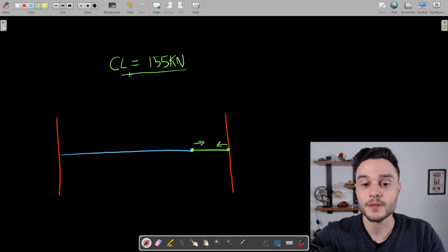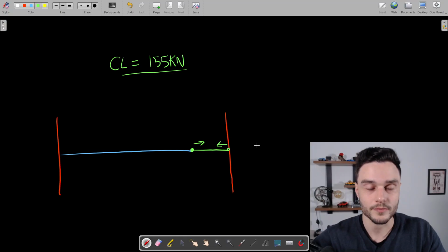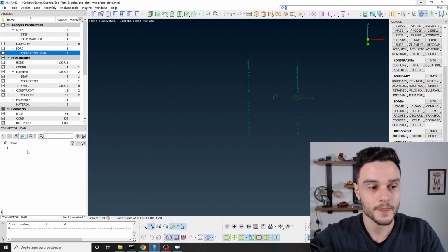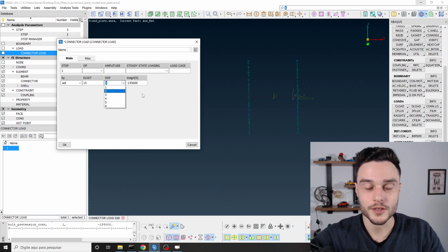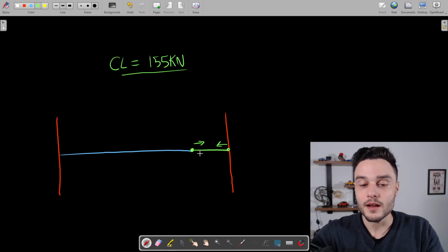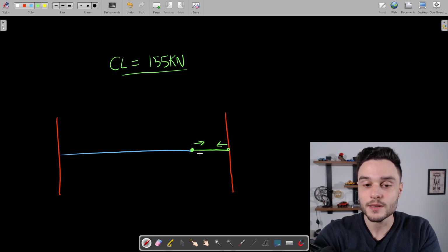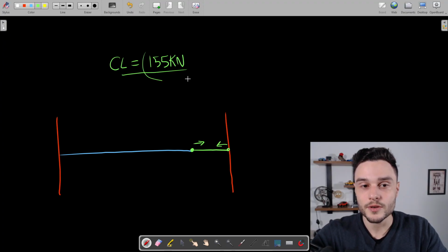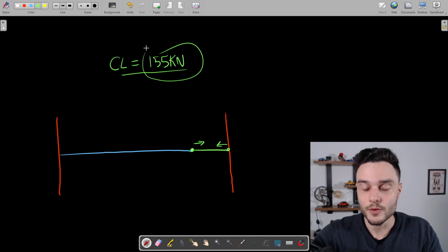Okay, so the software applies a displacement, a relative displacement at these nodes in the direction 1, because we have defined it here. Direction 1, x1, in the axial direction of that coordinate system. And then it calculates a reaction force that this displacement produces. And then it does that until this force is reached, right?